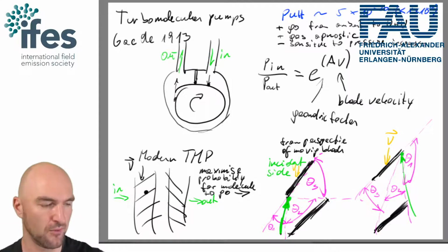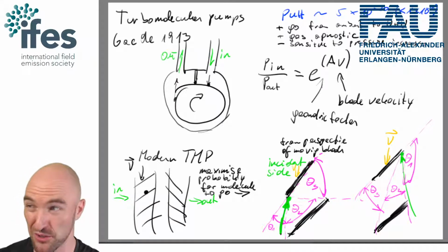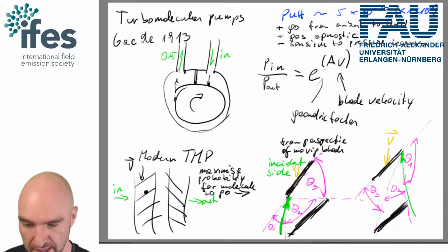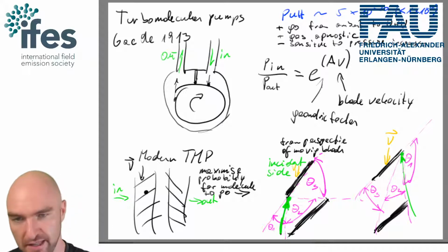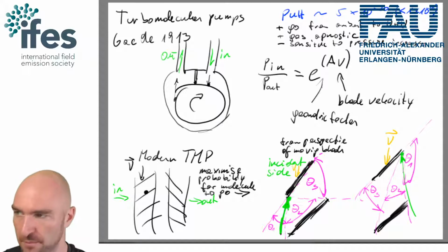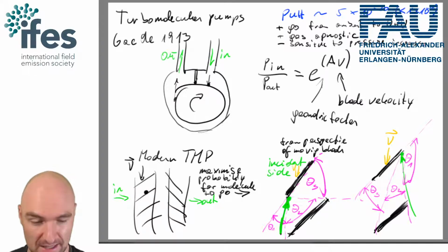So if you suddenly put a lot of gas into your system, your turbo pump might not like that, and that is because it spins very fast. So if you suddenly get pressure in, the bearings might start seizing up. Modern pumps can take that a couple of times. Older pumps were really bad at taking that.